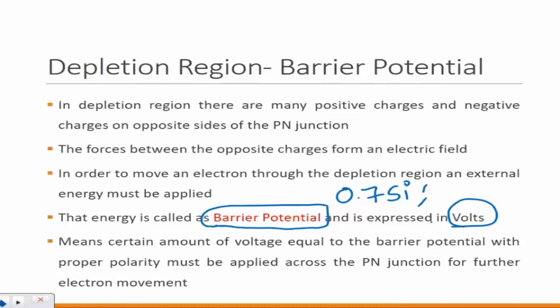So for germanium-based diodes or germanium-based semiconductors, it will be 0.3. It is possible, we need to look at the data sheet, but for the safe operation, this is what it is. It's always going to be like that. And if you apply a specific temperature, there may be a possibility that it will be 0 volts altogether, but that may defeat the purpose of semiconductors altogether.